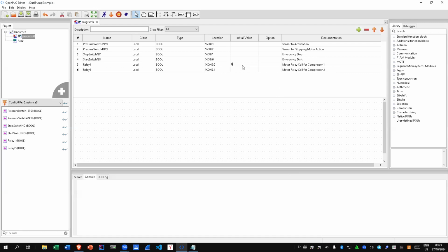Again, here we assign a value since we do not want the relay to be prematurely activated. If your relay is activated by 5 volts, you need to place in 1 if you want to activate it, or 0 if you want it to be deactivated. I'm assuming that will be the case, but in the laboratory setting, we all know that the relays we're using are inverted.